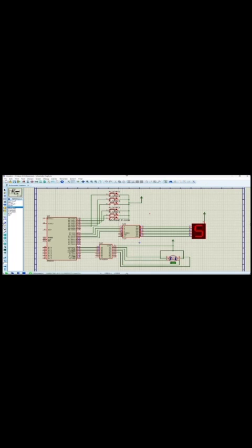Next, U1, the 89C51. Based on the pressed button, the microcontroller activates the motor to move the elevator to the desired floor. It sends a BCD code to U3 to update the floor number on the display. It outputs a 4-bit BCD on port 2 that represents the current floor. Like if the ground floor was selected, the BCD will be 0 0 0 0. If floor 5 was selected, 0 1 0 1. As a binary coded decimal, it is represented.